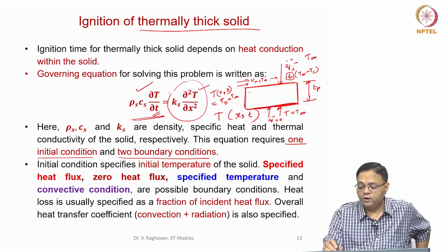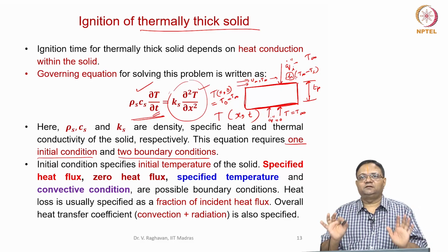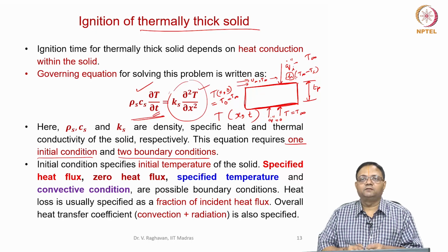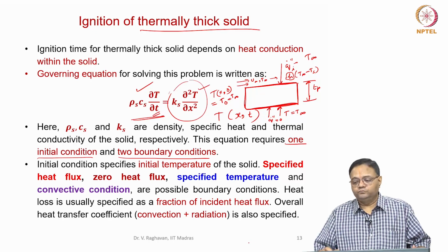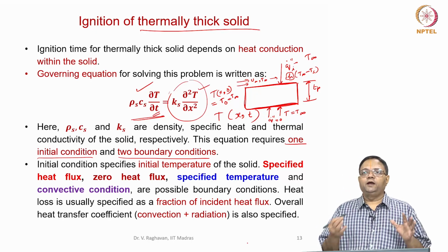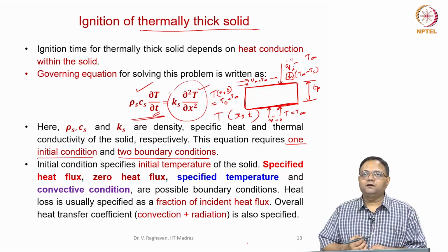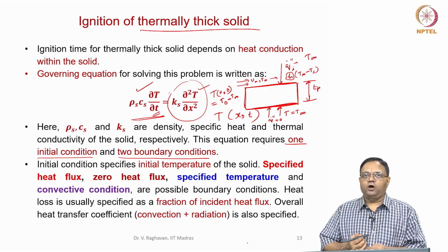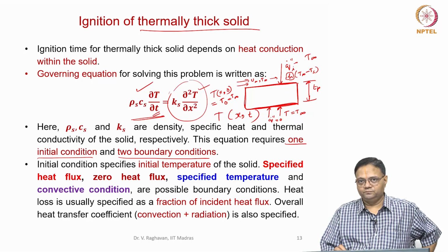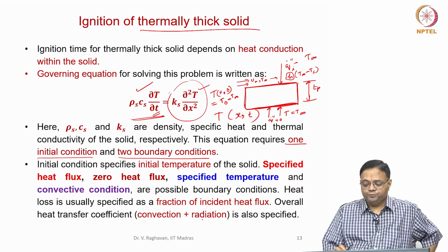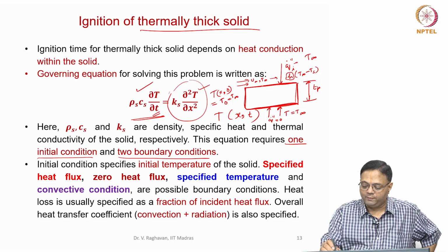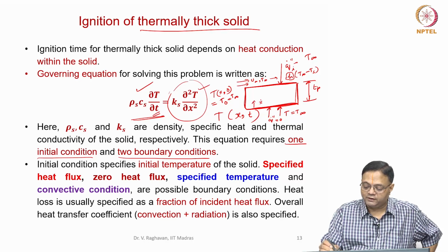Do you understand? So, the problem is just a heat transfer problem. The problem to understand ignition of a thermally thick solid is nothing but the heat transfer problem, where I try to heat up the solid in a time dependent manner, solving a one dimensional transient conduction equation. Do you understand? So, as I told you, the boundary conditions are important. I do not really care about these two sides because it is only one dimensional heat transfer I am solving. This is my x direction now.